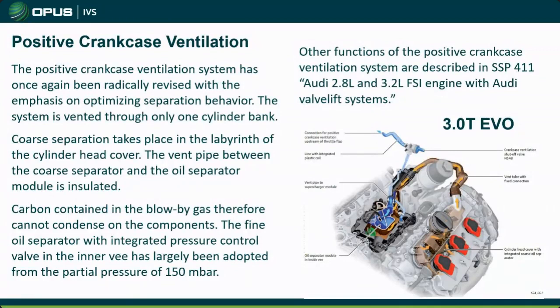So I'm not going to go through all of this in here. You guys can come back and read it word for word. But a couple of things that I like to note about this system. First of all, you have that same kind of labyrinth, right? You have it come down into this breather system here. You still have your air coming in from the outside, but what they've done here is put this crankcase ventilation shutoff valve in, and that's kind of an interesting thing here, because what they've basically done by putting this here is when they shut this valve, they stop the flow of crankcase pressure or crankcase ventilation.